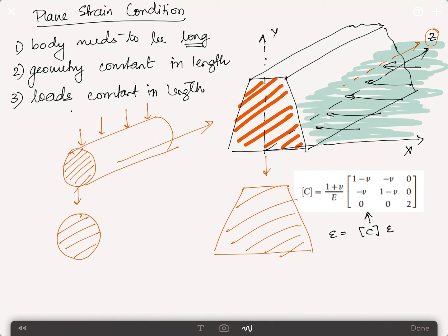Now the same way, when you want to make a plane strain problem, you follow the same path as you did in Abaqus for the other problem. That means you do the 2D planar, you apply a solid homogeneous part, you tick on the plane strain condition, and in the elements you define plane strain as the element you want to use. Now what if you are using Patran?